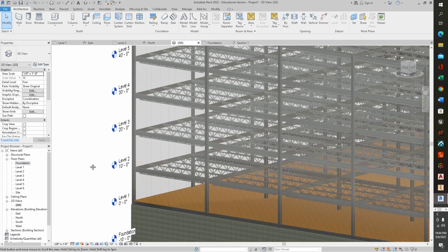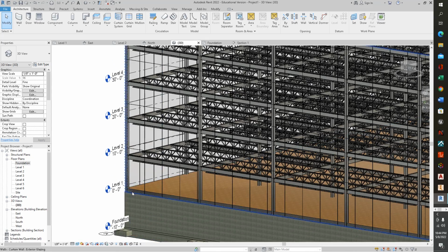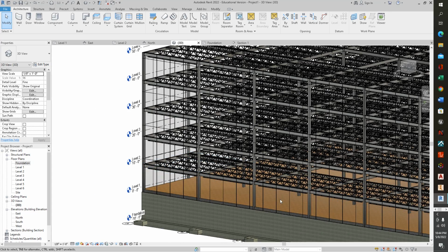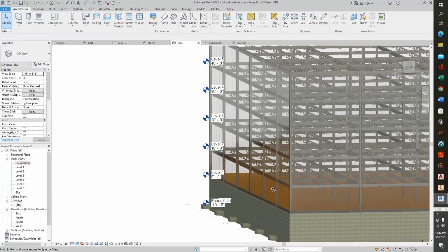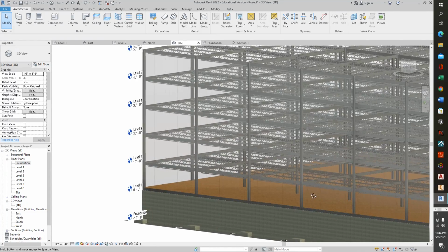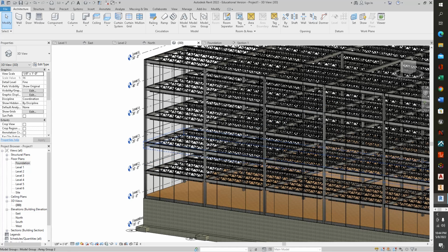But yeah, anyway, as a long story short, we'll say that we're going to offset everything that we're putting into here by 12 inches, the thickness of the floor. And that's just fine. We'll just know that the floor is 12 inches thick. So we actually can do that to all of this all the way up if we'd like to. We could copy that into each floor, or maybe we'd like to have a different floor for each one of these things, and that's fine too. But that's how we're going to get the floors in there.